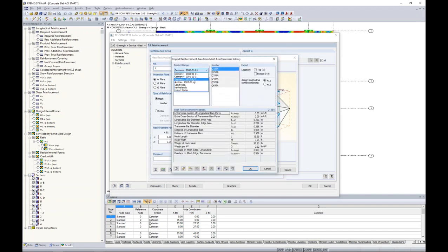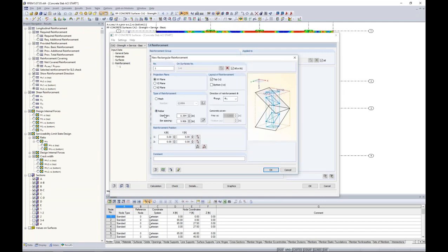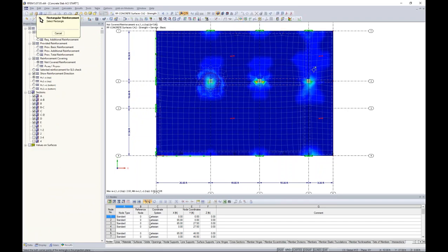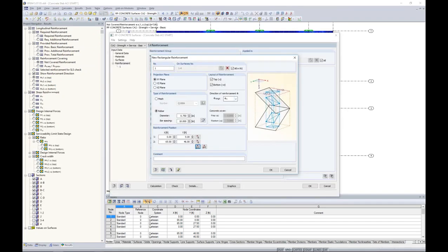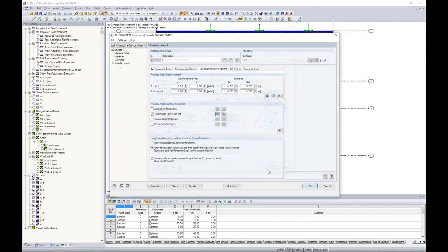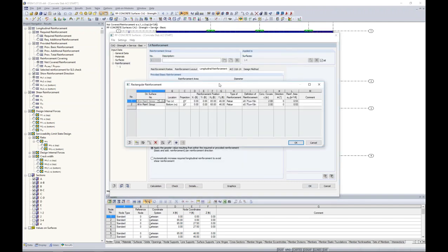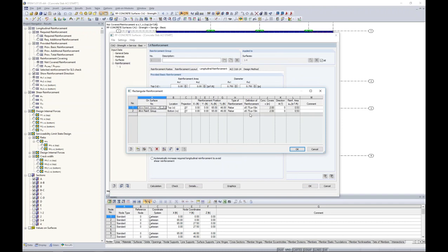Again, we can pull out this welded wire reinforcement if we'd like according to these rolls or sheets, or we can define our diameter of our rebar at 0.75 at 10 inches on center. Now, I want to apply this to both the top and bottom in the 0-degree direction. And I simply choose my 2 points to apply my number 6s at 10, and I'm going to choose the entire slab here. I click OK, and now I have this table available that I can see I've applied to both top and bottom in the 0-degree direction, number 6s at 10 inches on center.